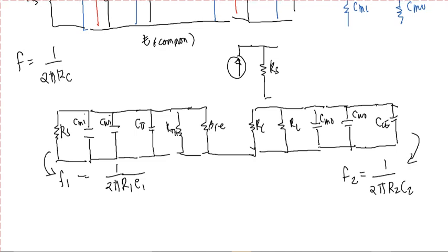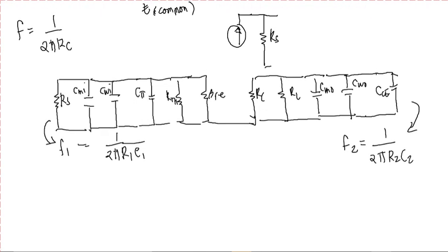For our values, we base our R1 on the sum of all the resistance values at our input. So this will be RS, parallel with RTH, and then parallel with beta RE. Then substitute it into R1. This will be our first formula.